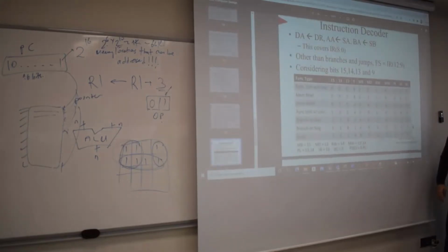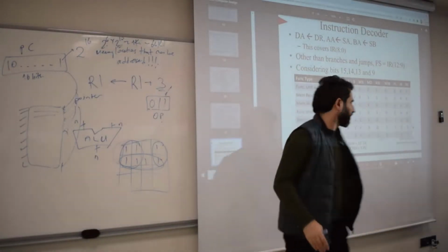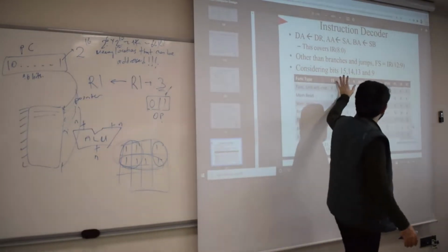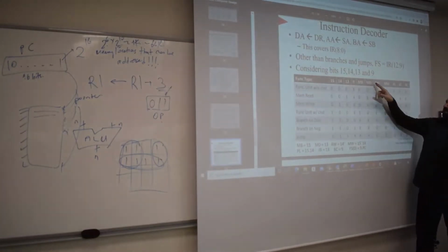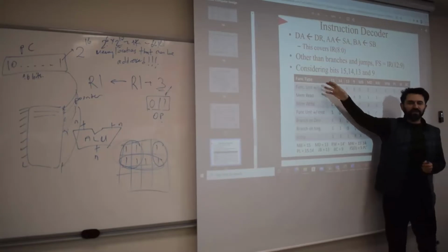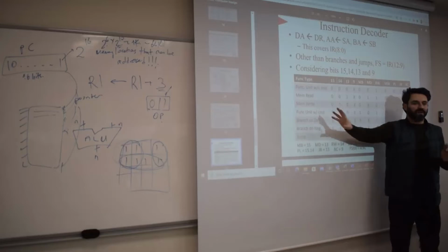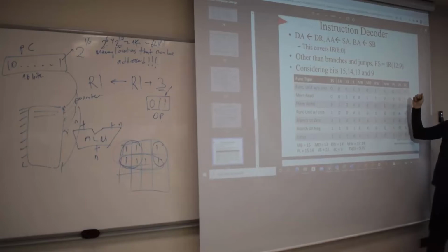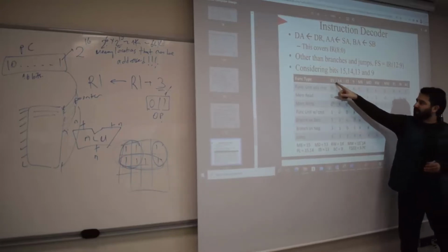Okay, this is the general section. Here, you don't have to put everything in, but we actually did a classification of these instructions, such as function unit without a constant. What happens to these bits, starting from 15, 14, 13, 9, and MB, MDR? Why am I starting at 15? Because the rest of them, destination register, source register A, source register B, are simple, right? You don't have to change them, just copy them. The rest of the bits are important, this one, 15 to here, BC, okay? And you see 13, and these are also probably function unit here, so it's already known. So these are the important ones.